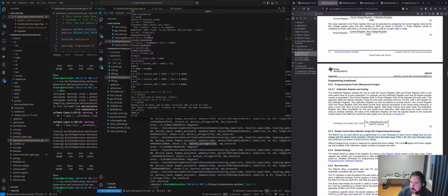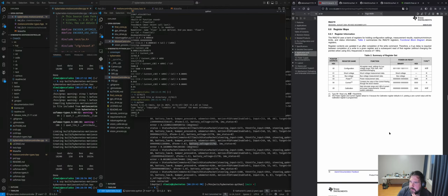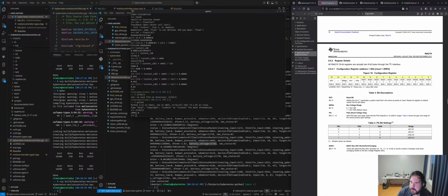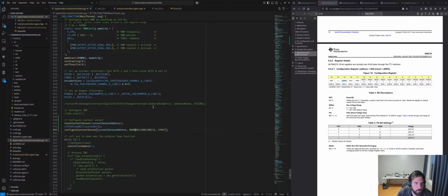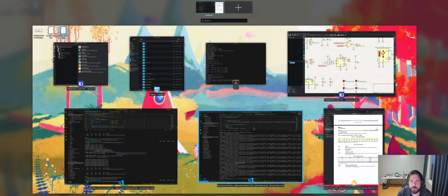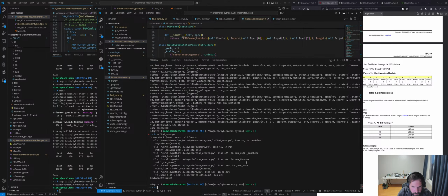Bus full scale range. What if I actually programmed the full scale range? Maybe that's the register. Let's just see what happens. We just got to flip one bit in the configuration. So if we did the full range, if we change that 13th bit to 1, we copy that back over, go back to our robot.